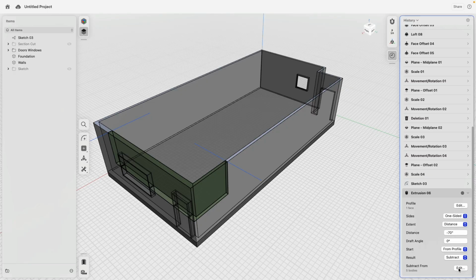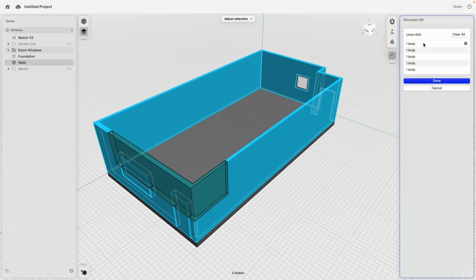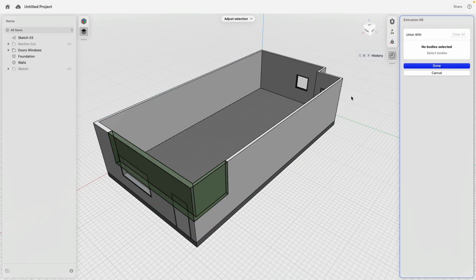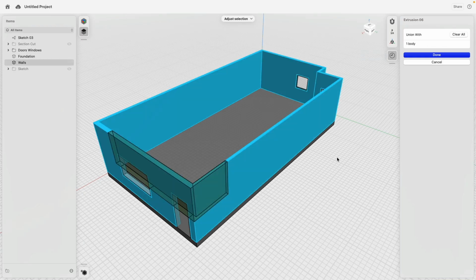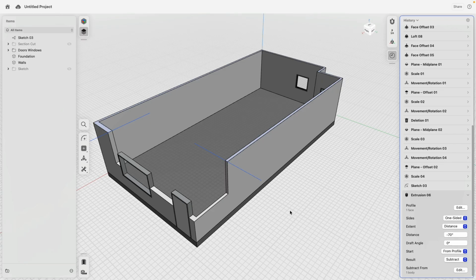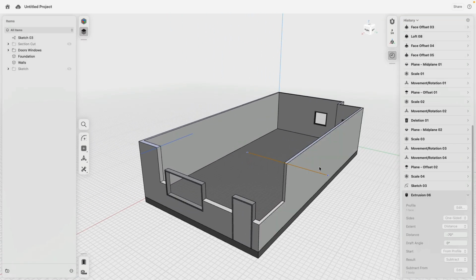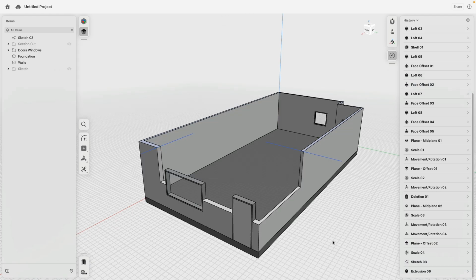To only cut the wall, but not the window and door, I can remove those from the auto selection. So this is actually the wall. You see how this is highlighted. So all the other objects I can remove. If by accident you have removed also the wall, just when everything is removed, just select it. Done. There we are. Again, with this, we can adjust that.